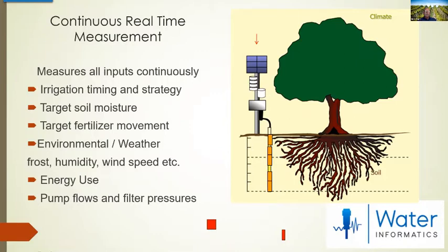That system ought to be run, in that 2-inch infiltration rate soil, that sandy soil, if my active root zone's at 12, I probably ought to run it between 6 to 8 hours, turn the system off, and then come back and do it the next day. Again, PG&E incentivizes us to run low cost energy.